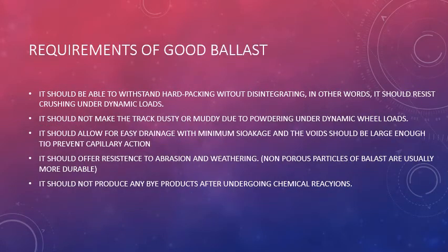Now, the requirements of a good ballast. It should be able to withstand hard packing without disintegrating. In other words, it should resist crushing under dynamic loads. While trains move over the ballast and the rails, they cause strong dynamic loads. These dynamic loads can cause breakage of ballast. So the ballast should withstand these dynamic loads.